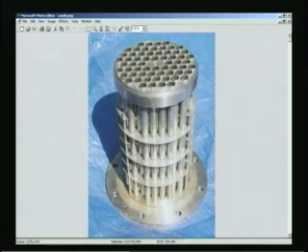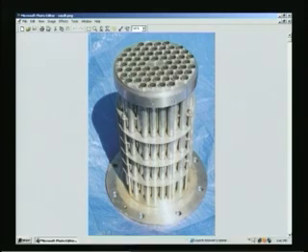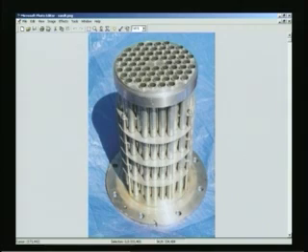All right. This plate at the end is the tube header sheet which I described, in which the tubes are fitted. This is the other tube header sheet at the bottom, and you can see it is on a flange there because it has to be fixed to the rear or the front end head of the heat exchanger. And here you can see the baffles.